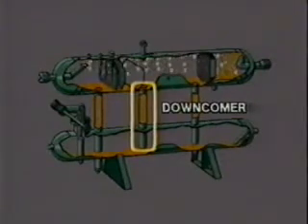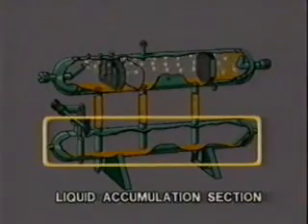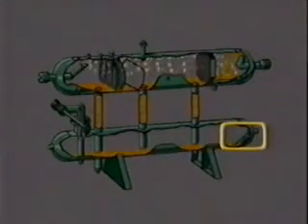The vertical pipes, or downcomers, extend into the bottom cylinder below the surface of the liquids there. Liquid which collects on the bottom of the top cylinder flows down through the downcomers into the lower cylinder. Here, sand and other solids settle to the bottom of the cylinder. Under control of the liquid level controller, liquid leaves the bottom tube through the liquid outlet.